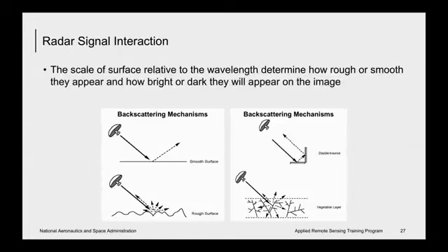And then you find this type of double bounce as well in flooded areas where you've got standing water and then you've got upright standing vegetation, and this creates very geometrical angles, causing a large amount of the energy to be double bounced and scattered back to the satellite. That's why flooded areas appear very bright. So finally, there's volume scattering, which is illustrated in the lower right image. And volume scattering is the scattering of radar energy within a volume or a medium.